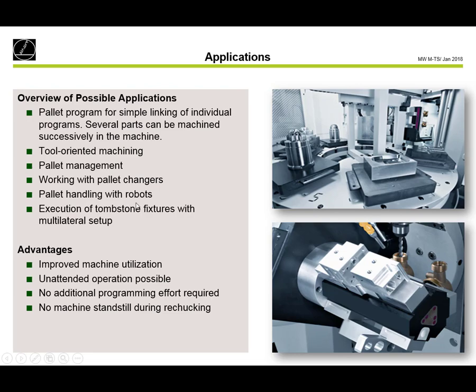So what are the advantages of pallet machining? I can save time because of tool-orientated machining. I can also get a really long runtime from the machines, because with a pallet changer, for example, I can machine 10 workpieces one after the other in a row. So the machine is running longer without a person at the machine who needs to change the workpieces.